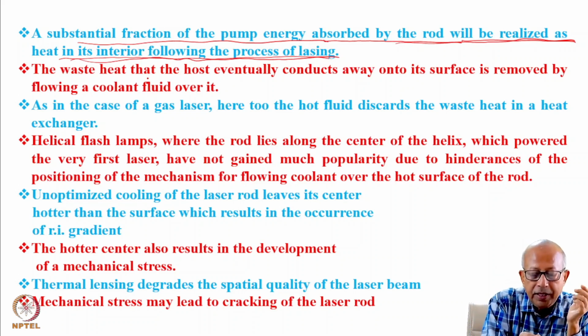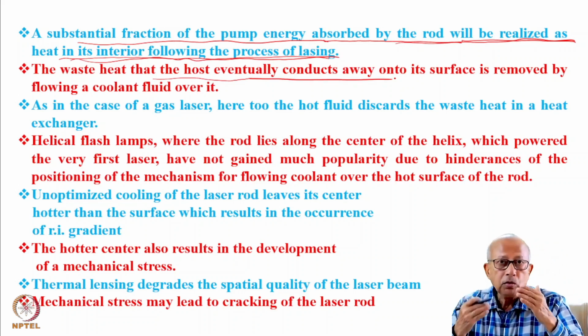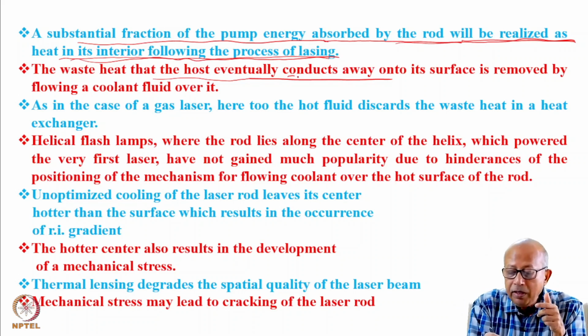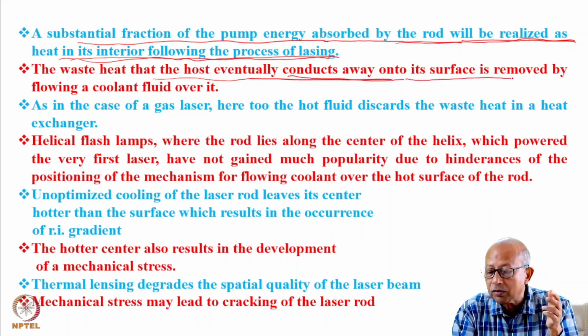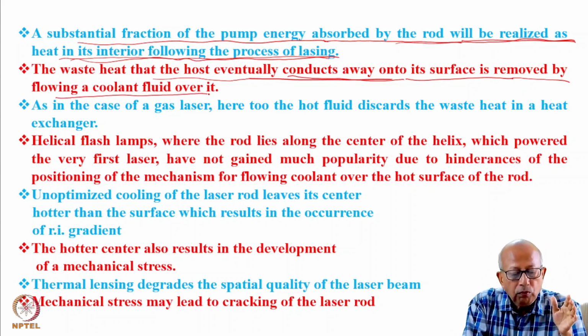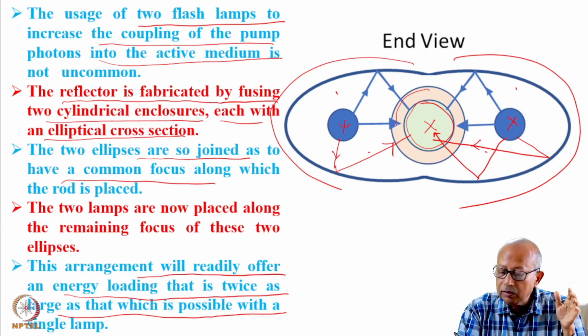Now this waste heat the host eventually conducts away, because we know the host has excellent thermal conductivity. So it rapidly conducts this heat onto its surface, and this is removed by flowing a coolant fluid over it. As you can see, this is the jacket around the laser rod, and coolant flows through it and removes this heat which is conducted away onto the surface.